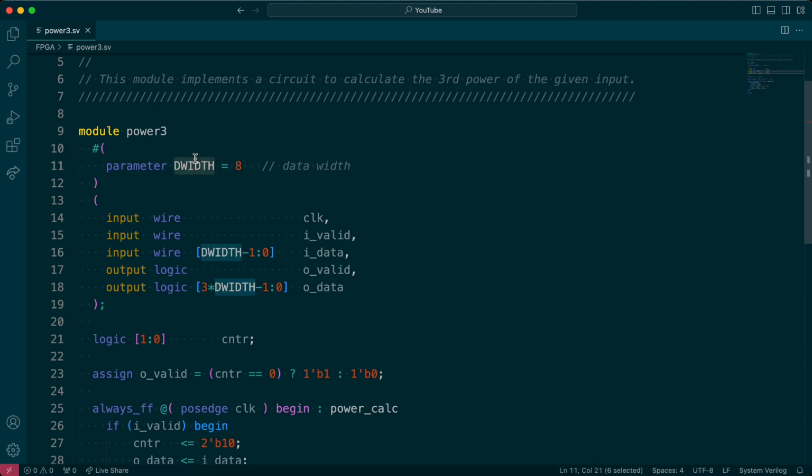So it's about 2.7 bits per clock. And then we did mention that the latency of this design is 3 clock cycles, right? Which means that once an input is valid, it takes 3 clocks for the output of that specific data to be valid. And also the timing is the delay of one multiplier in the critical path. So far, everything is so good.